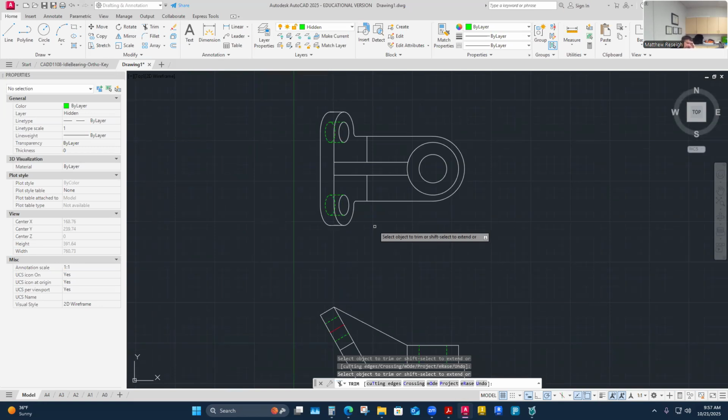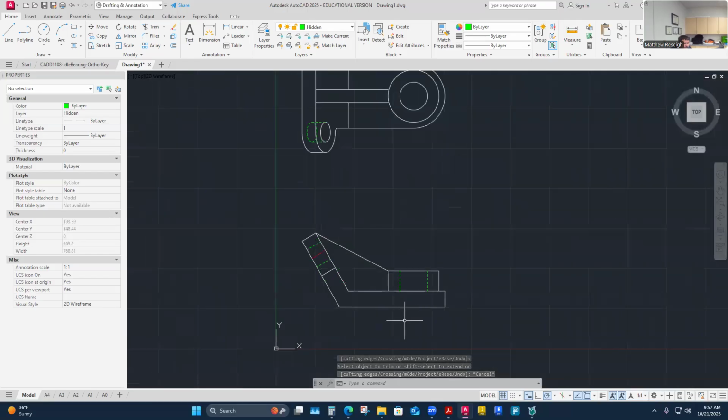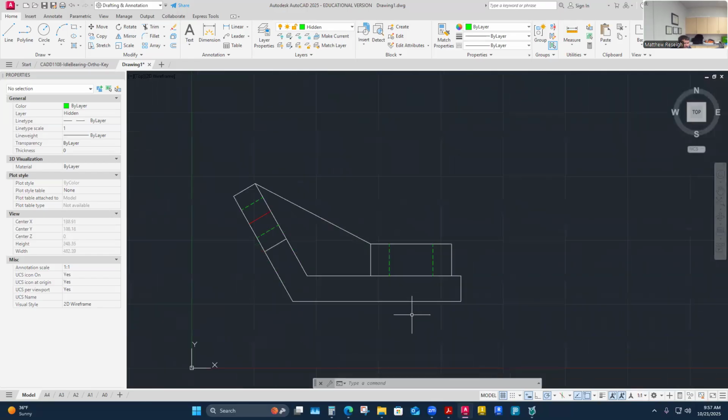That's definitely the lesson of the day. Ellipses, how to draw them. Establish a major and minor axis based off your projection. Yeah, I like it. That's the bend coming up. This is the surface that's foreshortened to me. So I just need some center lines to finish my views. And I need to continue this one through.